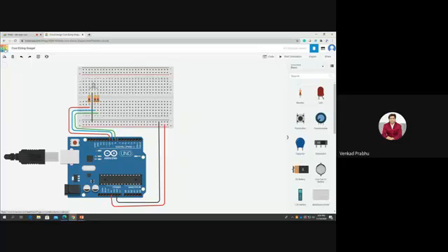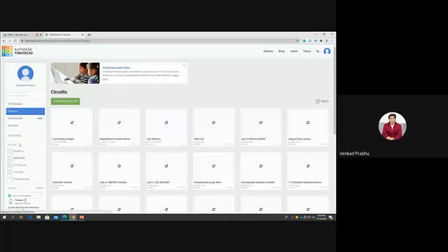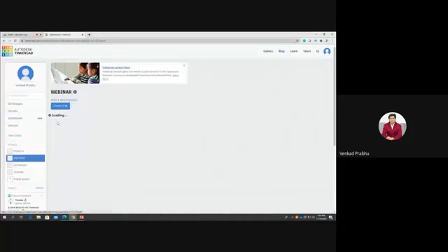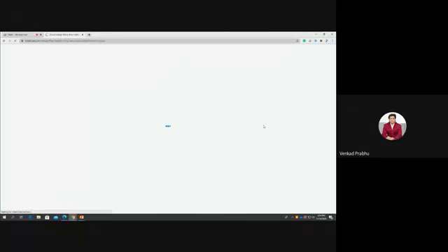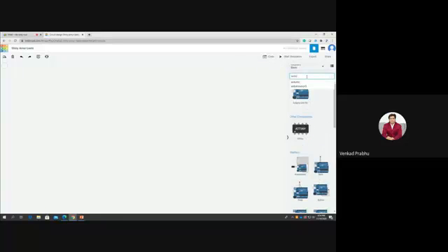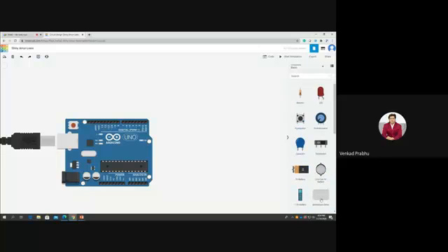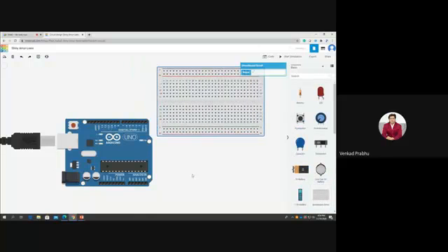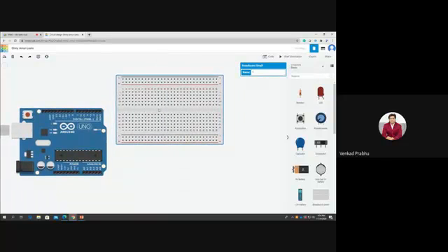Now I will do it with the program directly. I'm going for a new one. At least this part you can start up. This could be somewhat interesting with the temperature sensor. So go to the home page, create new circuit. So here I am going to use Arduino. So again, here Arduino board and breadboard. I'm in need of a breadboard small. So here I can move this Arduino to this side.